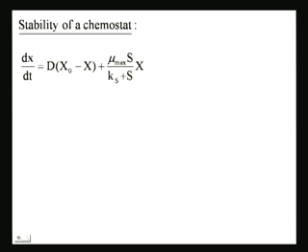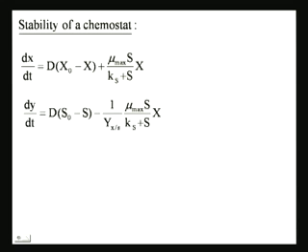Then the next question comes: what model do I use for this specific growth rate? I can use different kinds of models for specific growth rate. As a result, when I'm doing this analysis, I want to do it for mu, so that I can plug in any kind of growth rate at a later time, and the analysis would still be valid. Is it clear? I think that's the major thing: you're not differentiating between the growth rate as a whole and the fact that you're using just Monod growth kinetics. You can use a modified Monod growth kinetics, you can use Malthusian kinetics or different kinds of kinetics.